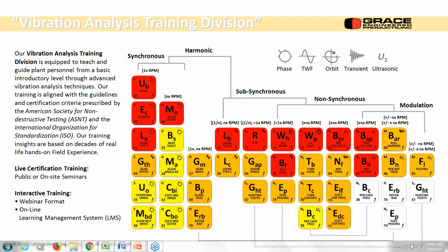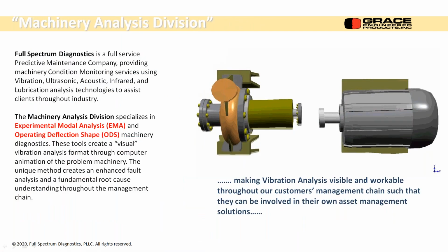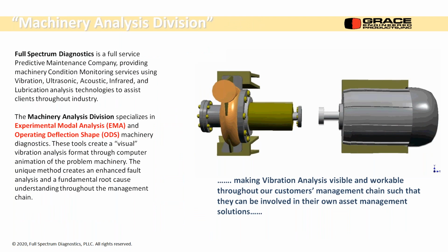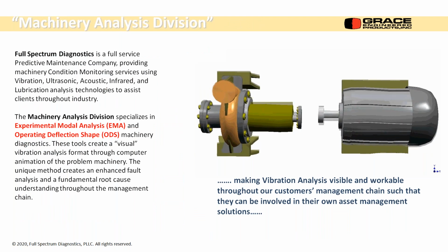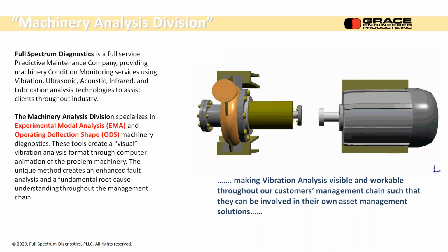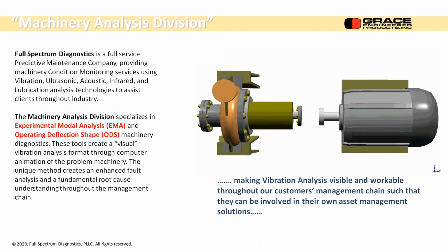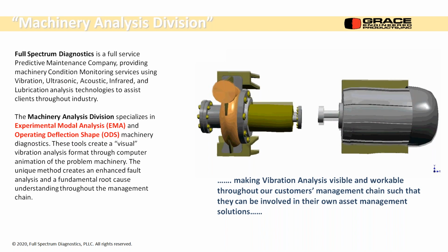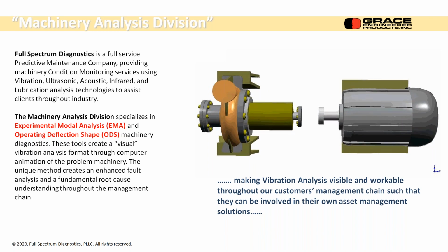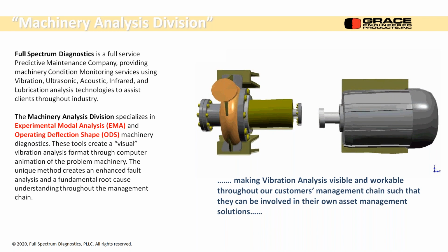Our company also has a machinery analysis division. I mentioned this on Tuesday, that we do experimental modal analysis, which is looking for natural frequencies in structures, and operating deflection shape, where you're trying to get operating information about your machinery and trying to diagnose its response.